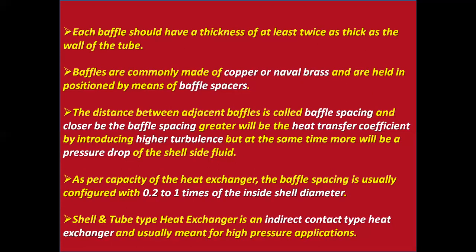The distance between adjacent baffles is called baffle spacing, and the closer the baffle spacing, the greater will be the heat transfer coefficient by introducing higher turbulence, but at the same time, the more will be the pressure drop of the shell side fluid. As per the capacity of the heat exchanger, the baffle spacing is usually configured at 0.2 to 1 times the inside shell diameter.